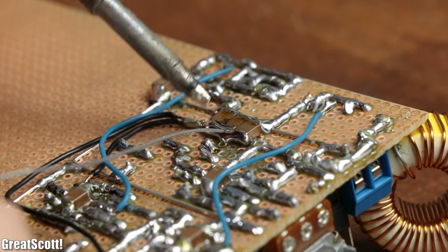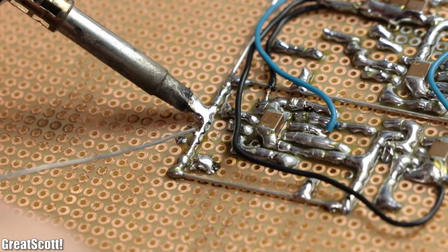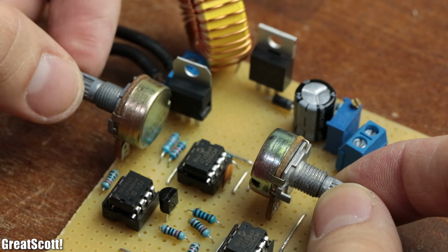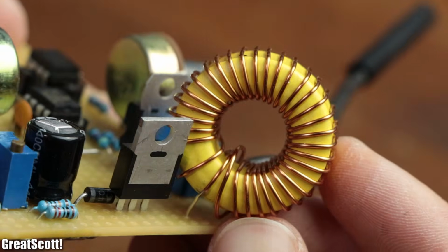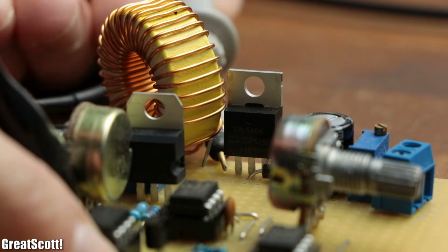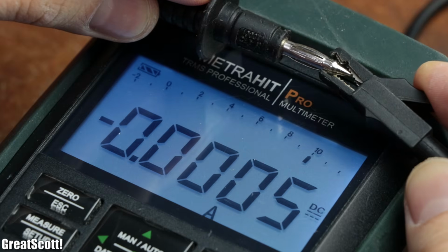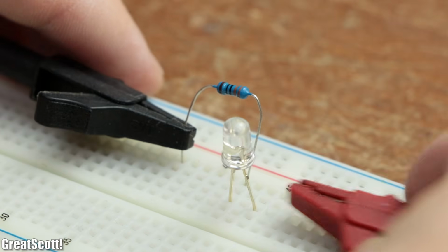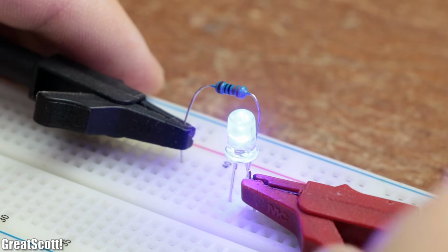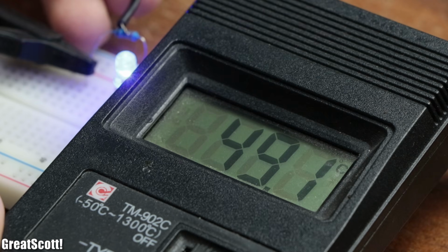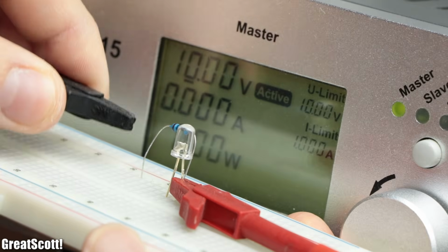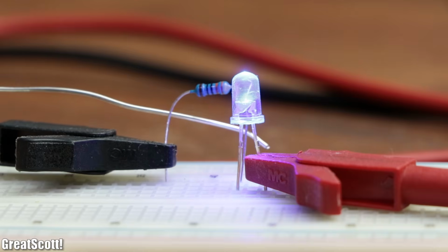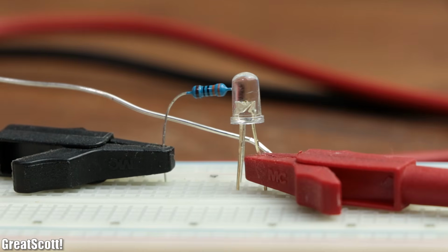When it comes to creating DC circuits, like I do in around 90% of the cases, then the function of the most basic passive components, the resistor, the inductor and the capacitor, is pretty straightforward. The resistor, like the name implies, resists the current flow, and thus can be used, for example, in an LED circuit to convert the excess power into heat, so that our LED can shine with the correct nominal current flow, unless of course someone evil shorts the resistor.